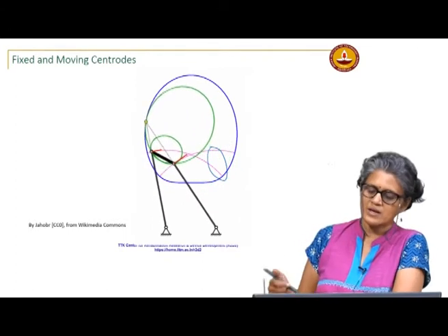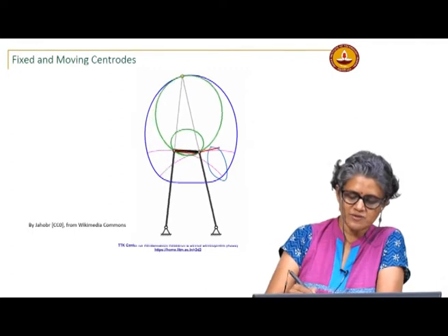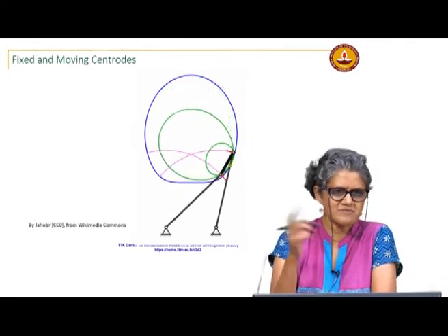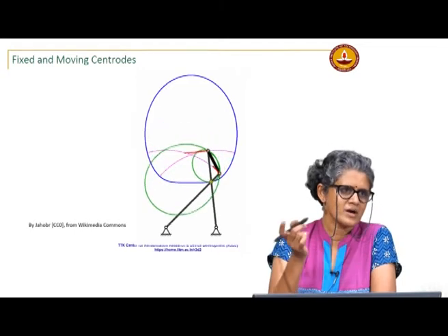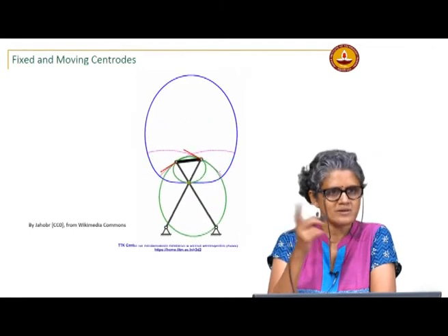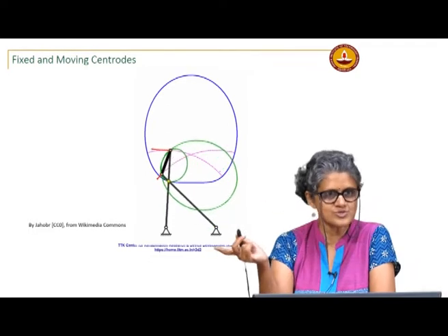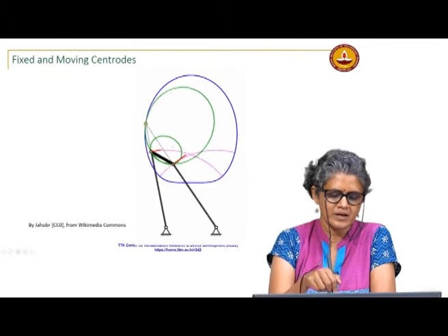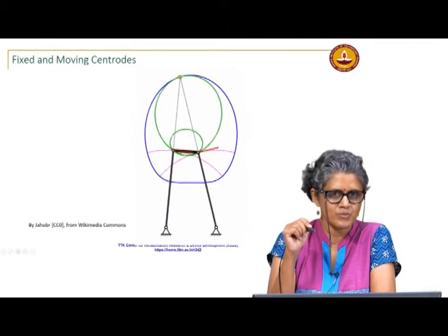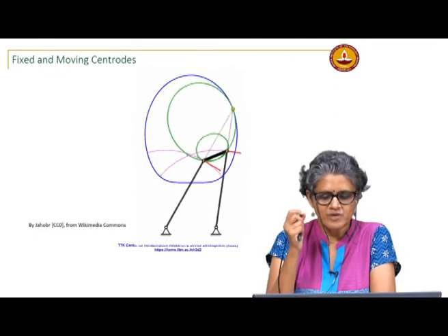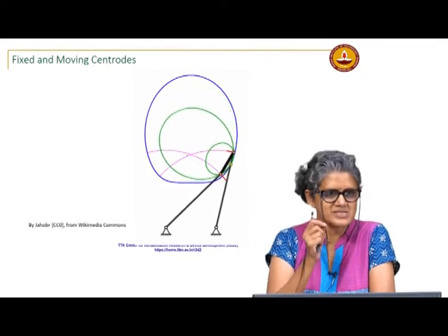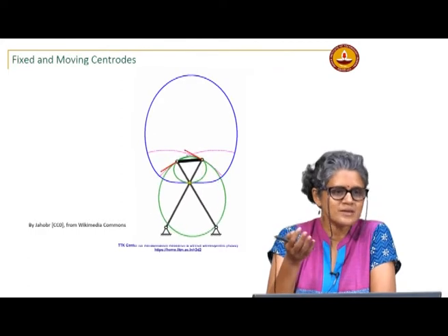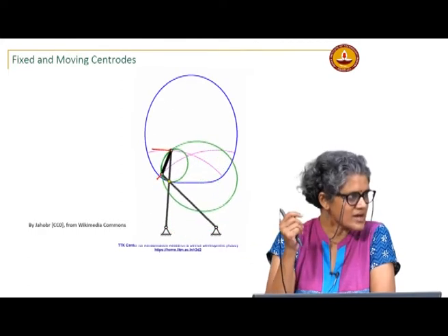But I need to do some reading on that to see. But these 2 points, yeah, because you do have reversal of motion, even with the crank rocker. If you look at it, the velocity goes to 0, then it reverses. So, that is what the coincident points are in this case, but we do not really treat those two pivots as coupler points, because you are not going to get anything more interesting than a circular arc.